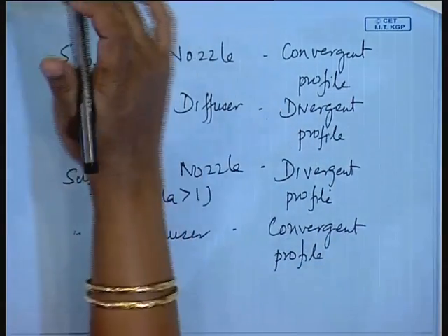Okay. So, this is something very important that you should be noting, that the behavior of compressible flows is not consistent over the entire range of Mach number. One type of flow characteristics is exhibited for Mach number less than 1 or under subsonic conditions, just the reverse type of phenomena is observed for supersonic conditions. And that explains why this particular fact, Mach number equal to 1, is so very important. For Mach number equal to 1, it is termed the choked flow condition, or the condition of choking.